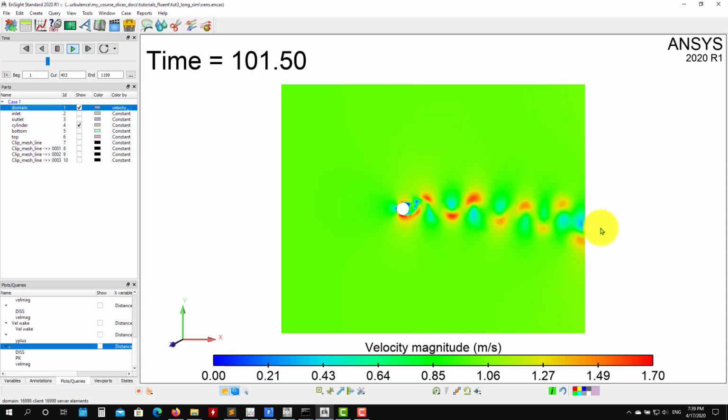It's difficult, but since LES is resolving everything and not adding any modeling here, we can capture that switching and those turbulence structures that are probably causing it, generating that switching through the interaction, because here you have many vortices and a strong interaction. You see that even at 120, 130, there is still some switching.